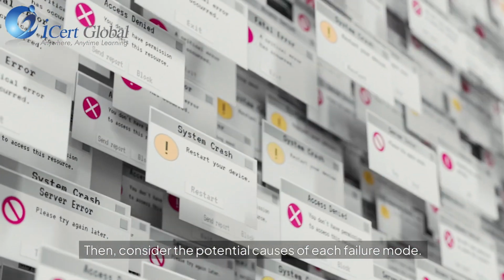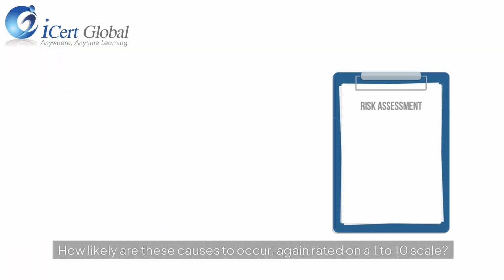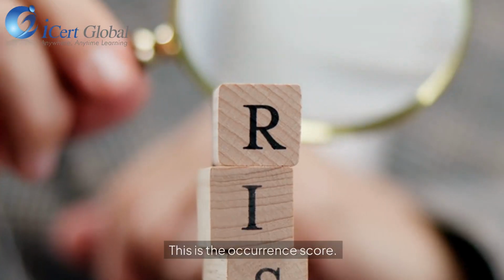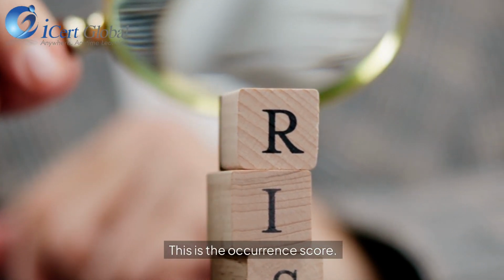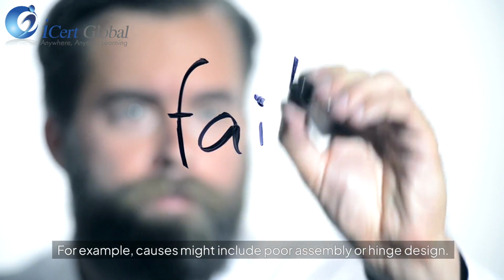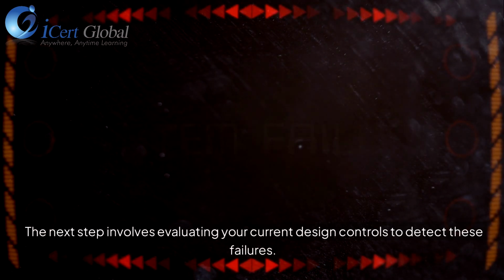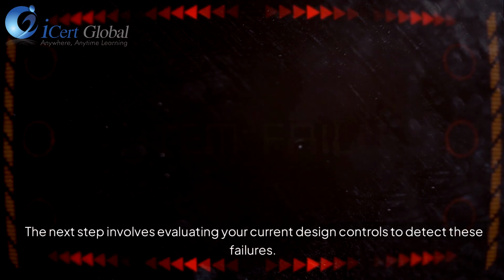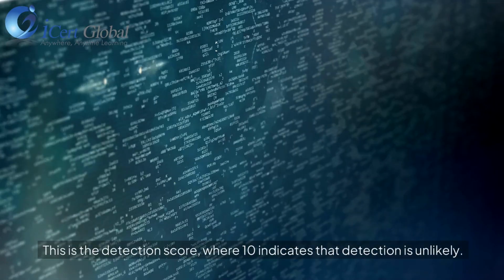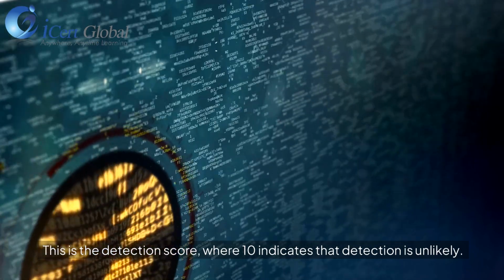Then, consider the potential causes of each failure mode. How likely are these causes to occur, again rated on a 1 to 10 scale? This is the occurrence score. For example, causes might include poor assembly or hinge design. The next step involves evaluating your current design controls to detect these failures. How likely is it that these controls will catch the problem? This is the detection score, where 10 indicates that detection is unlikely.